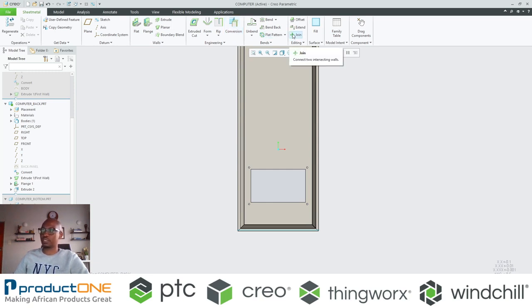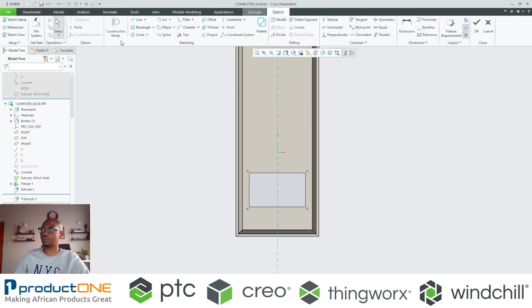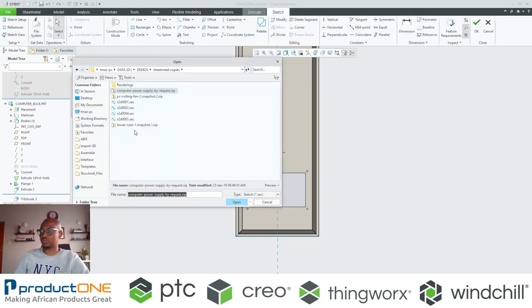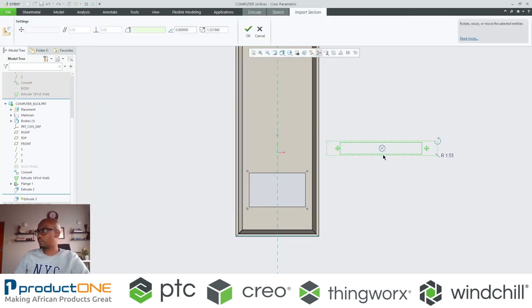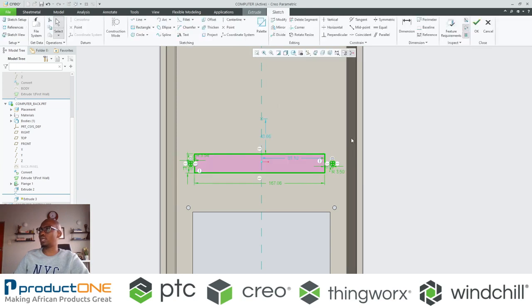Maybe a couple of other things as well is I can create numerous slots, which we will take full advantage of later on. So just as you've seen, I'm just going to pull up a saved sketch, just simply drag and drop. So there's nothing to it because as you can see, these are normal rectangular sketches with holes on either side.